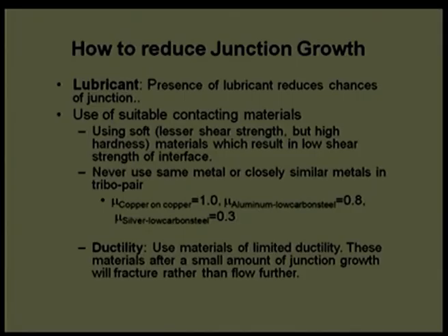Sometimes we play with the ductility also. We use a low ductile material which can be easily ruptured. Apply slight force on that, it can be easily ruptured at the interface, and that will provide a low coefficient of friction. However, there is a problem. If that rupture happens to be very rapid or it deteriorates the surface softness, then we should not use this kind of suggestion. We should use some sort of lubricant, or many times we use water to lubricate the surfaces.